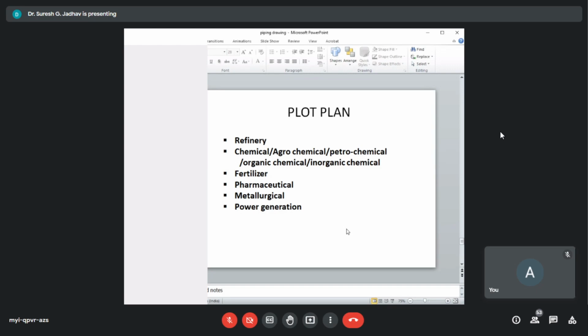Development of a plot plan is a much involved job. While locating the various units and facilities within the plot, consideration shall be given to the operation, maintenance, and safety aspects related to the plant and that of the neighbors, fire hazards, location of power and water supply, expansion facilities, and man and material movements in a balanced manner.